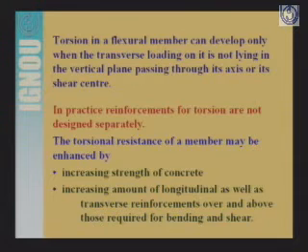Because we are already providing the longitudinal and transverse reinforcement for bending and shear, if we increase that amount, then the torsional resistance of a structural member can be enhanced. So these are the two remedies, but generally we go for the second remedy.